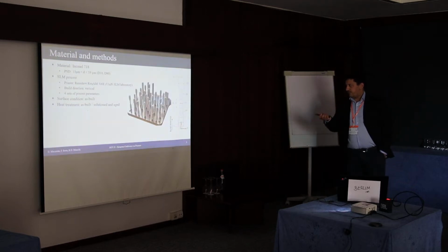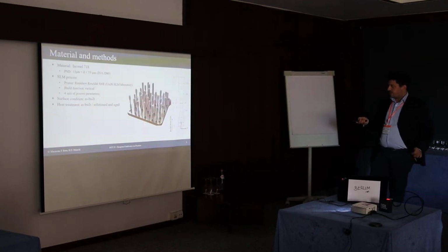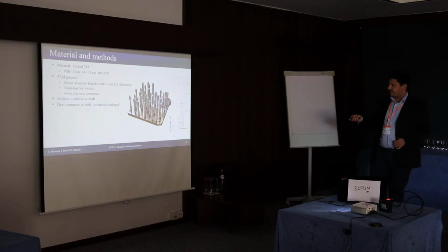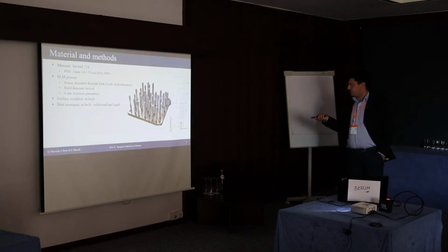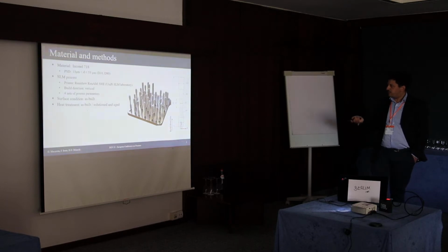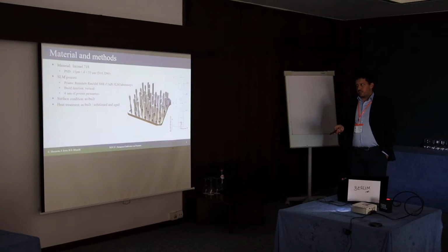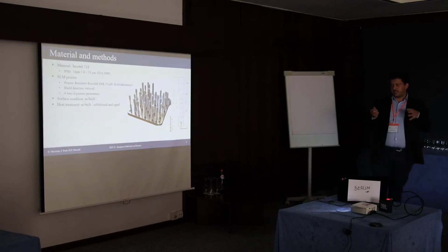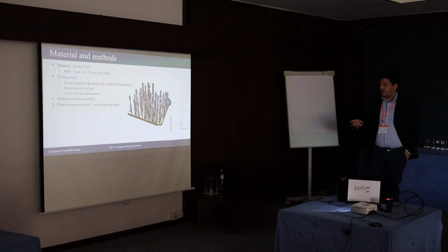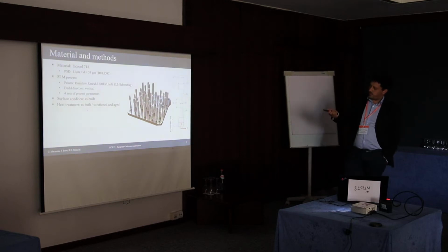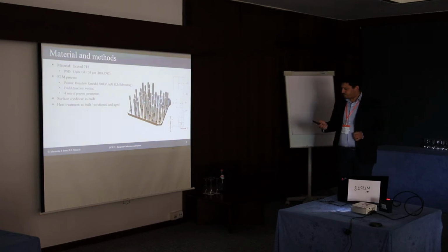All the specimens were built in the vertical direction. Here you can see the specimens on the plate, and on the right the standard dimensions. This is the dimension for the fatigue specimen, the tensile one is similar, just with the normal adjustments. The surface condition investigated is only the as-built surface condition, because we want to understand the effect of surface roughness.